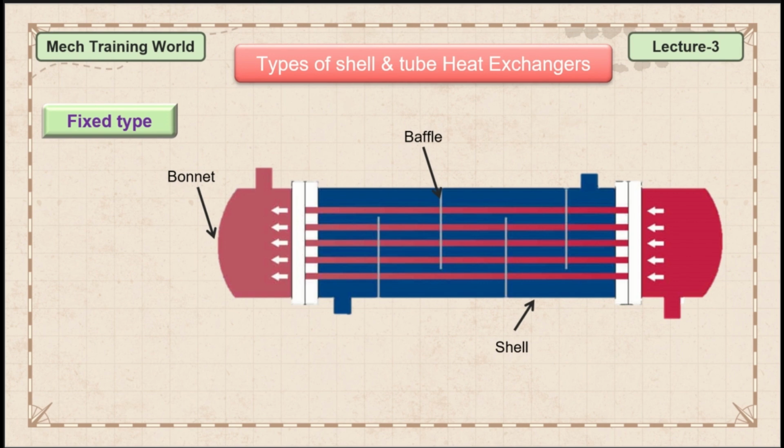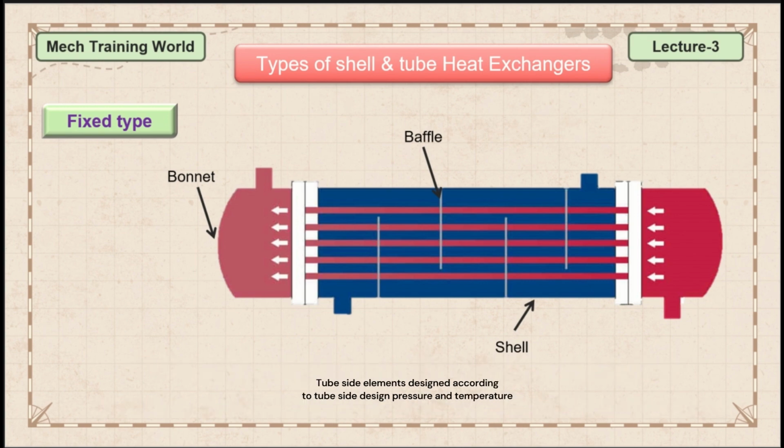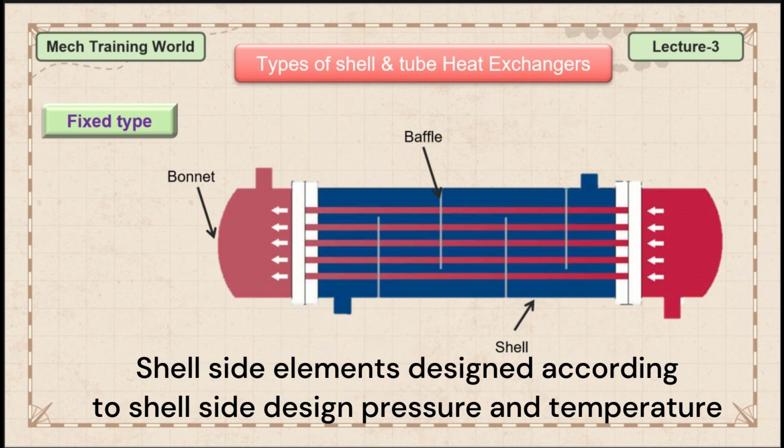It is important to understand the difference between tube side and shell side elements, because the design pressure and temperature must be applied accordingly. While designing the tube side elements, we need to consider the tube side design pressure and temperature. While designing the shell side elements, we need to consider the shell side design pressure and temperature. I hope you got that point.